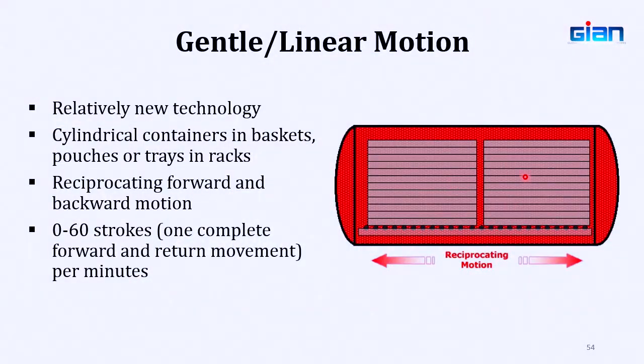And if you had to create relative motion between the two products to allow a faster rate of heat transfer, how would you do that? So they do it in this kind of geometry, where you would lay your pouches or trays horizontally, in which you would have the liquid component of your food and the particle. And when you are allowing this horizontal motion, the effect of forces on these two is different, because the density difference between solid and liquid will allow a different amount of force exerted on those.